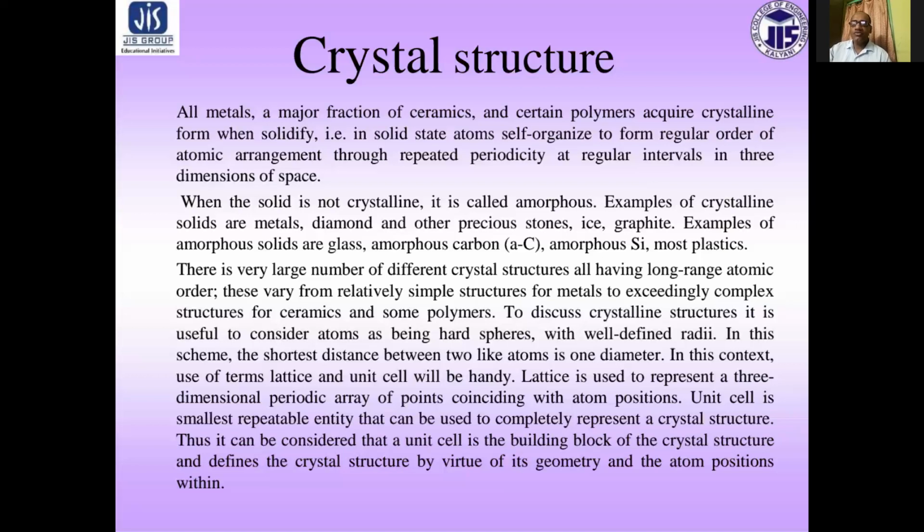So while dealing with crystal structure, the regularity of atomic arrangement in solids comes due to geometrical conditions which are imposed by directional bonding and/or close packing of atoms. The most stable arrangement of atoms in a crystal will be that which minimizes the energy per unit volume.